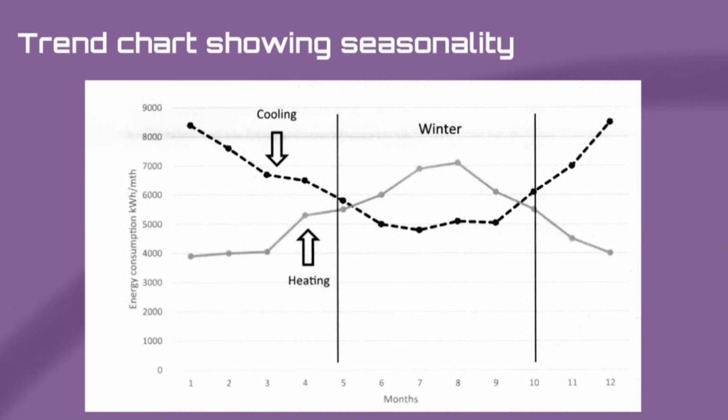A very well insulated building with high casual gains would probably be self-heating, and you wouldn't see that change in energy use as the season changed. You might see changes in cooling in that sort of building. In a building with no glazing and with a lot of process heat gains, it might be the process heat gains that are driving the cooling load rather than the weather. So sometimes including weather as a relevant variable is going to be misleading, and it isn't going to be having an influence on the information that you're monitoring.